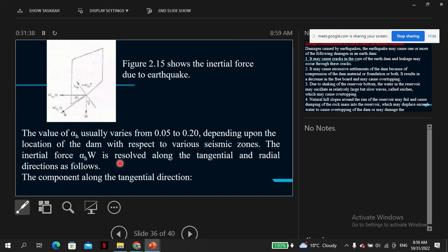What I mean is, in this country, the problematic area that we consider for earthquakes is usually the Rift Valley. In other areas, you have to do the calculation, of course, that is due diligence. But mostly you find that both wind and earthquake loadings are horizontal.